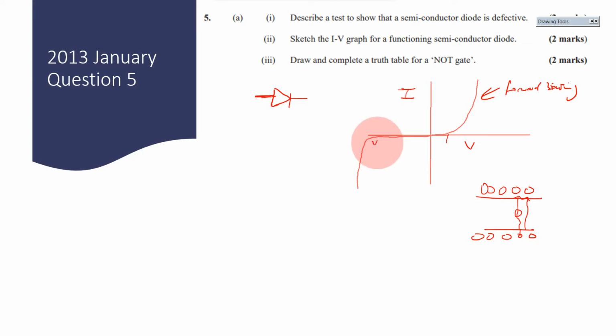So if you increase the voltage up to maybe about negative 50 volts or so, right, that in itself could damage or break down the operation of the diode, such that it allows current to flow through it. But as you can see, it requires a lot of voltage to do that, right? And whenever that happens, we are within the portion of what we call the breakdown voltage, right? So that particular voltage that causes current to flow in the reverse biasing position is called the breakdown voltage, and so on. So that's kind of what we're describing here in terms of the curve.